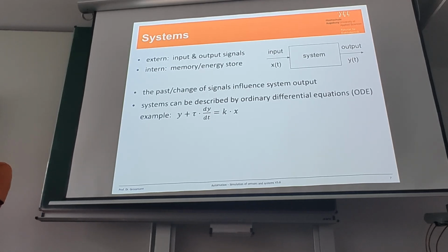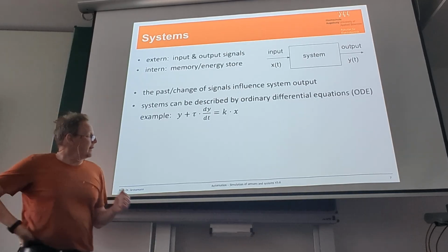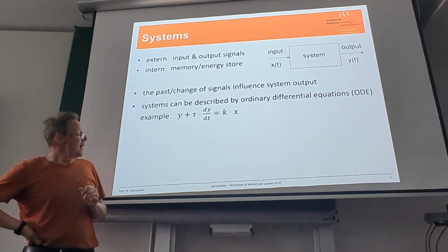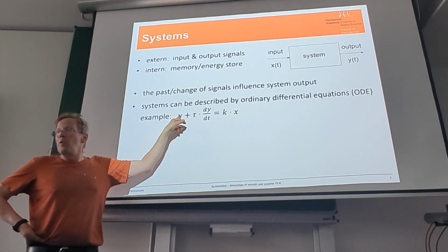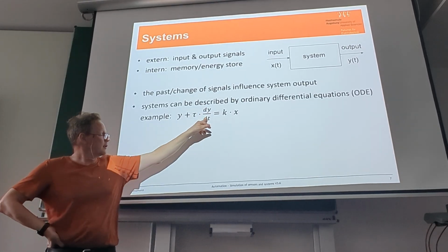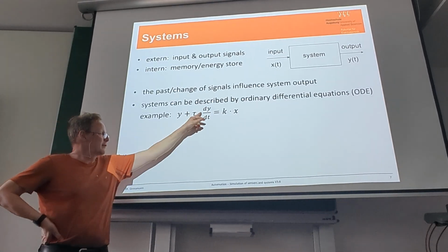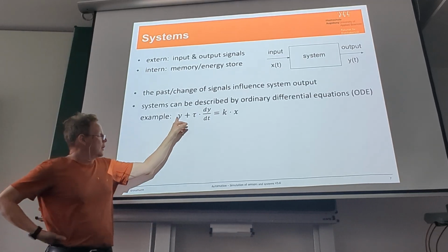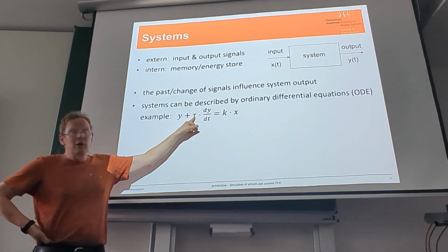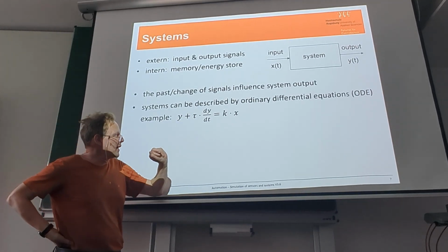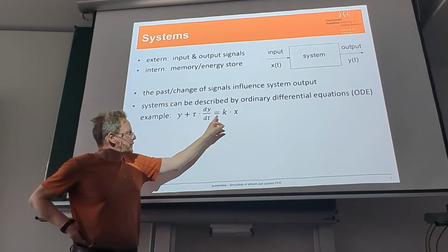The derivative is of the signal with respect to time, so dy and dt. So we need the same units for both terms. No matter what unit the y has, this term is this unit divided by seconds because of the derivative, so we first have to multiply it again with seconds, and then we can add the two quantities. Okay, so I know this must be a time, I don't know what's behind it, but this must be some time. And this is then connected with the input.